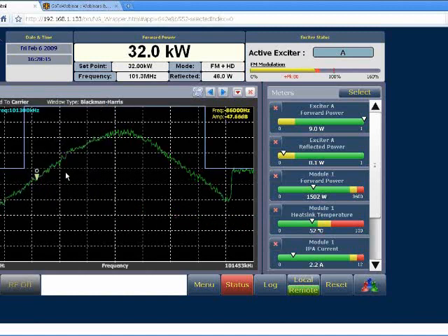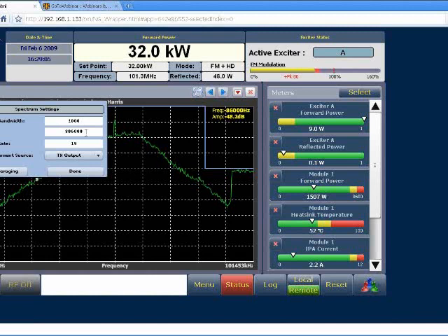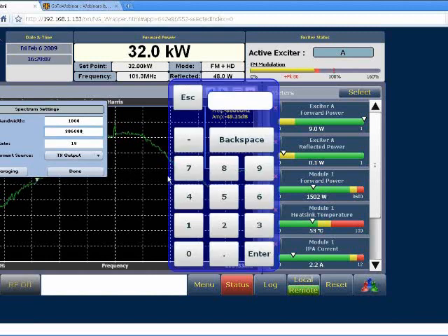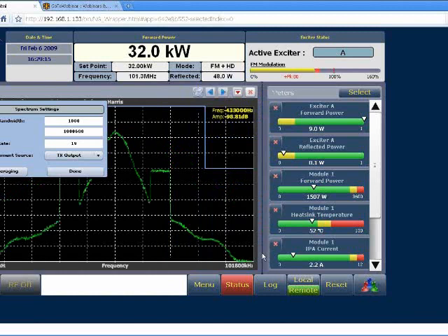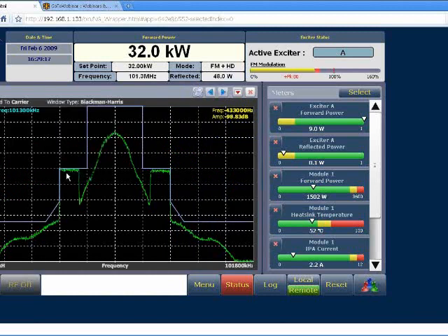And so I hit done. That's going to take a second to refresh and normalize. It should take just a second, I hope. And it looks like something started to happen. While that's happening, can you explain the meters over here? Check your span. I bet you're... Oh, okay, yeah. So in this case, the span was adjusted for the audio spectrum analyzer. Okay. So we'll set it up for a 1 meg span. Oh, yeah. Look at that. There you go. All right. Very good. So we're meeting the mask, a passing spectrum, what I like to see.